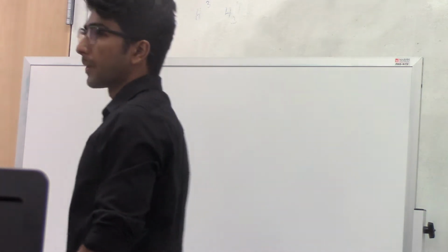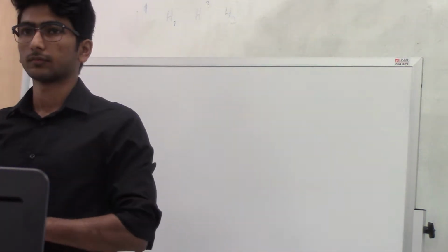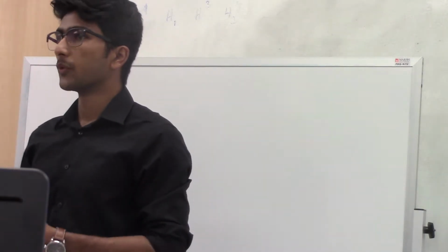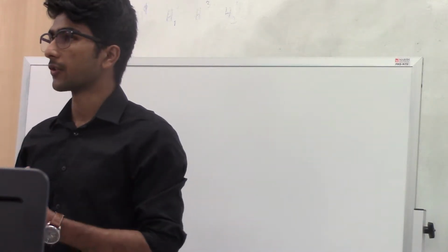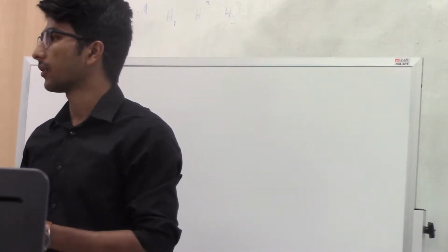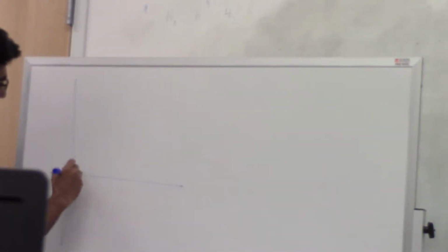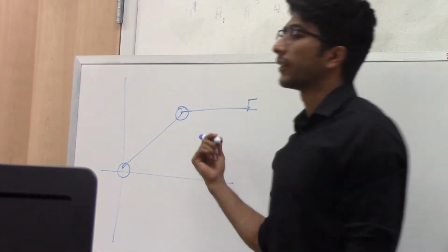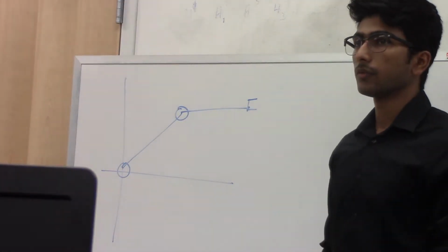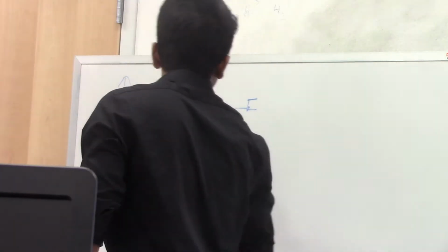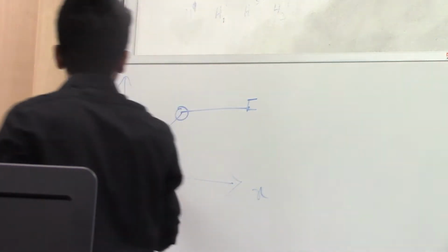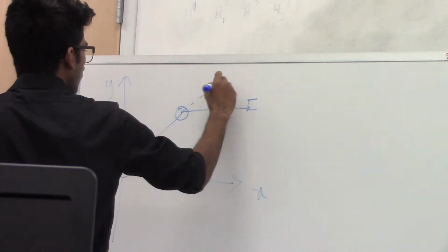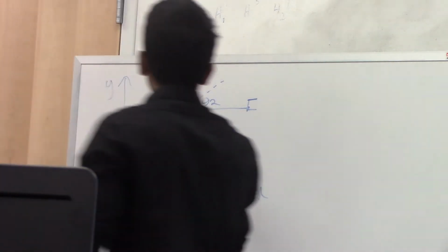So what is a planar manipulator? A planar manipulator just moves in a plane, only in 2 dimensions, so either xy, yz, or zx, not in 3 dimensions. Let's take a look at the DH notation for that planar manipulator. How many degrees of freedom do I have here? 2. So it's a 2 degree of freedom planar manipulator, and it will operate only in the x and y axes. I have θ1 for the first joint, and θ2 for the second joint.